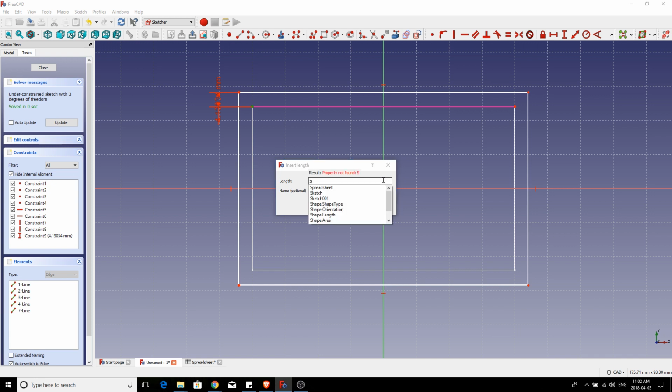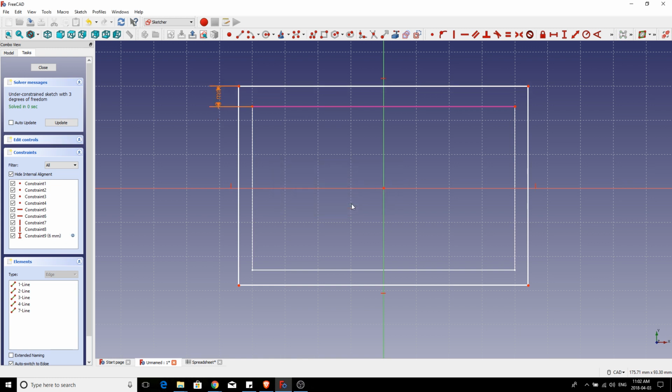We're going to go to the spreadsheet. And let's think about what we need here. So there's our card sitting in the middle. And we know that just around the outside of our card, we've created a card offset, just like that. But we're trying to model the outer walls of our box. So we're going to need to add in, once again, going to the spreadsheet, our wall thickness that we set in the spreadsheet. Going to hit OK again, and boom, there's the first part of our constraint.